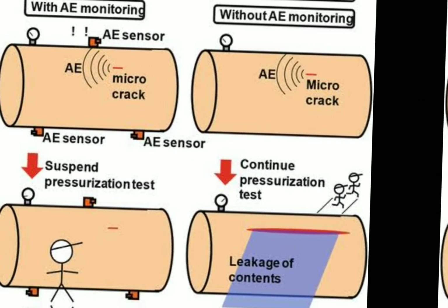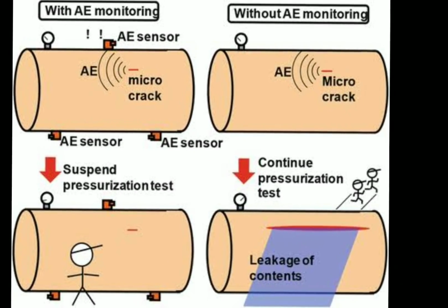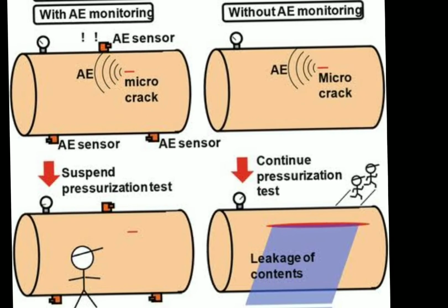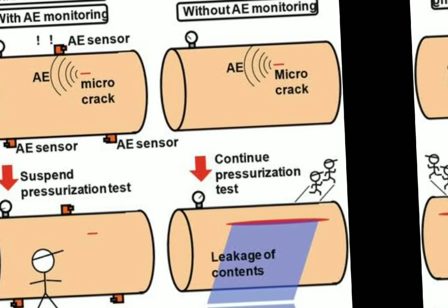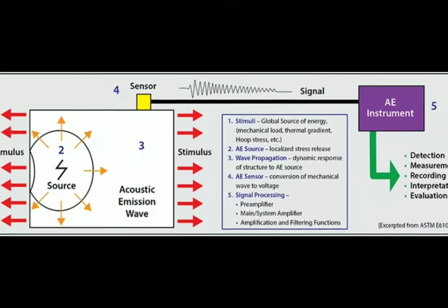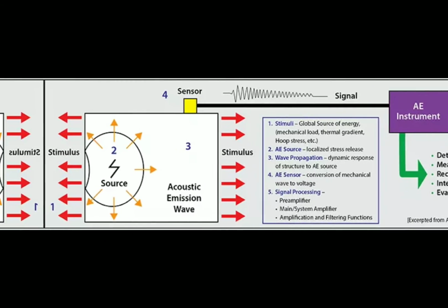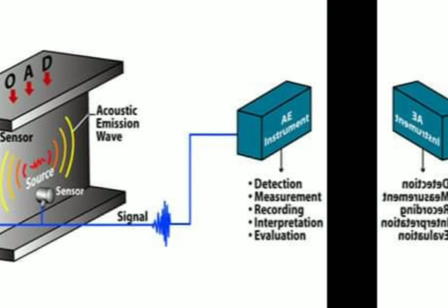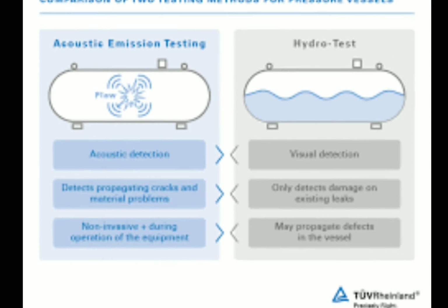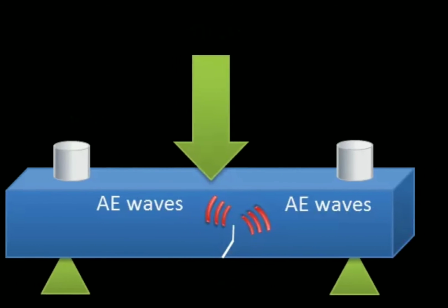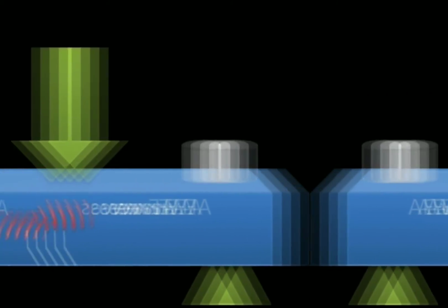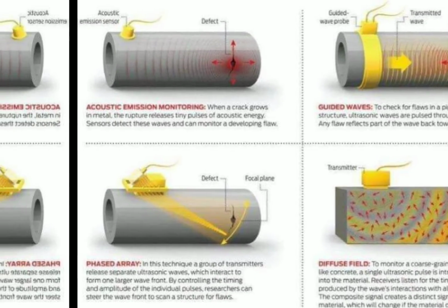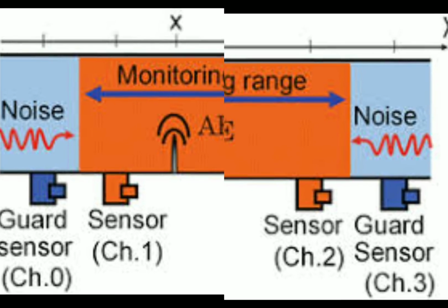Though the AE technique has been successfully applied for bridge monitoring, several challenges still exist. Bridges can create practical problems like, for example, accessing desired areas for a large number of sensors to monitor the whole structure. Identifying critical areas is the solution. For instance, in steel bridges, sources of AE include crack growth. The presence of noise sources can mask the AE signals from real cracks and is one of the biggest limitations of AE monitoring systems.